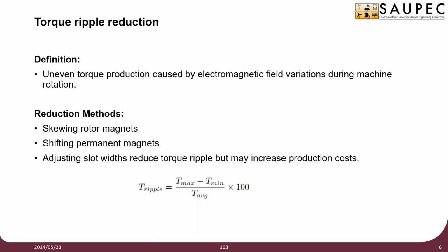The primary cause of torque ripple is the armature reaction. As the current increases, the flux shifts, which creates harmonics in the torque constant waveform. It can be reduced in a number of ways, such as skewing of the rotor magnets or stator slots, permanent magnet shifting, different slot width pairing, or reducing the flux harmonics. This study looked at adjusting the slot widths for torque ripple reduction.